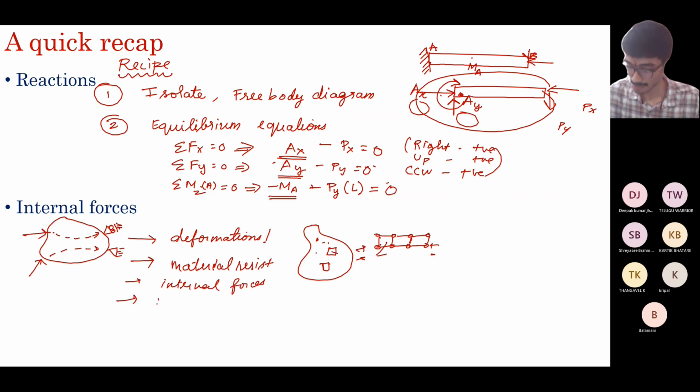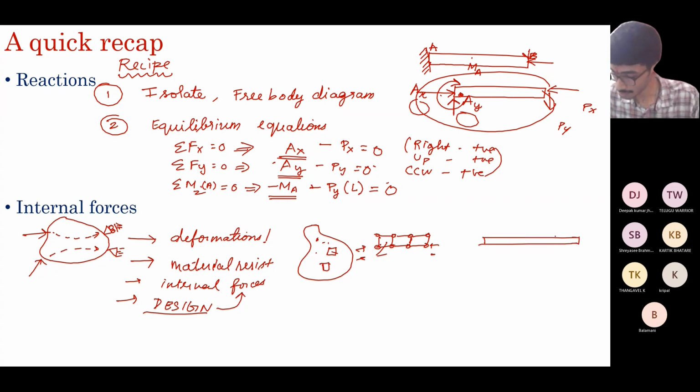We design all structural components for resisting these internal forces. For that, it is essential to know what the internal forces are. From Newton's third law, you know internal forces are equal and opposite for a structure that is in equilibrium. So if you consider the structure as a whole, you cannot determine the internal forces.